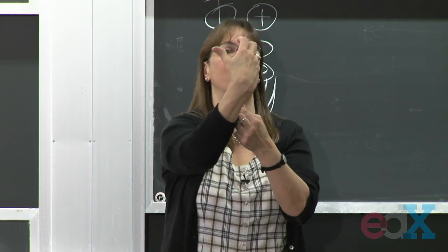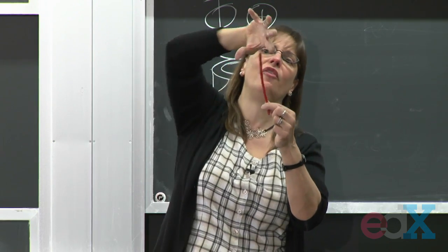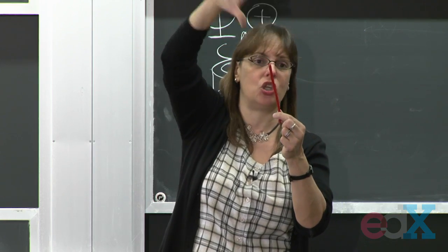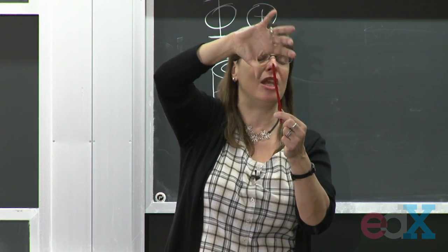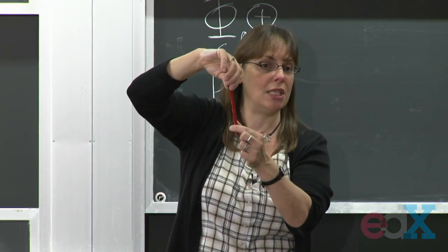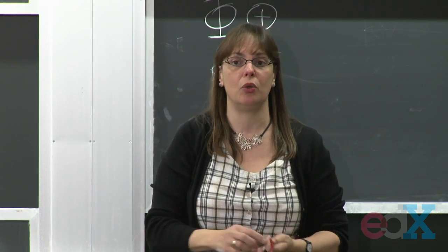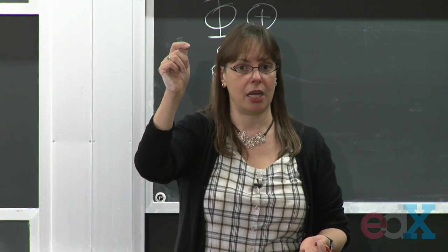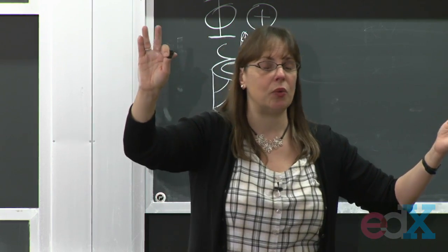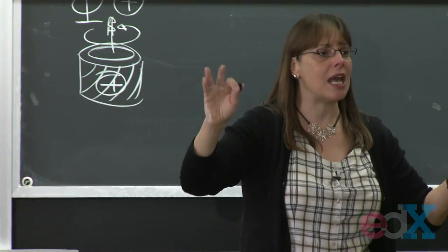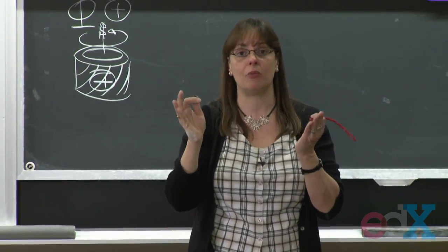And I describe the deformation, and I go with my fingers just along the deformation. I look at my thumb. If my thumb is in, the angle of twist is negative. If my thumb goes out, the angle of twist is positive. Clear enough? It has nothing to do with axis. Coordinate axis, nothing. It's a measure of the structural deformation.